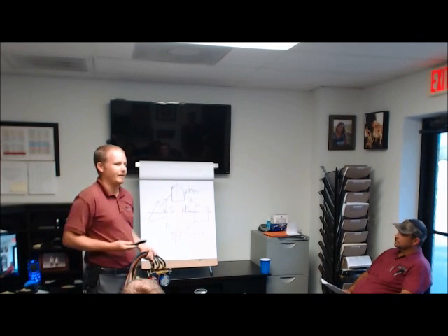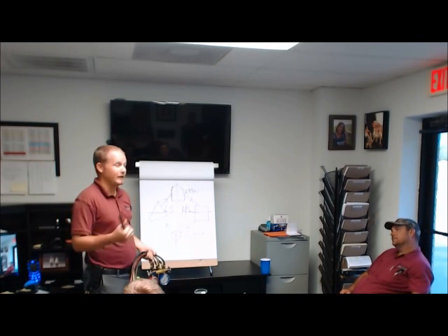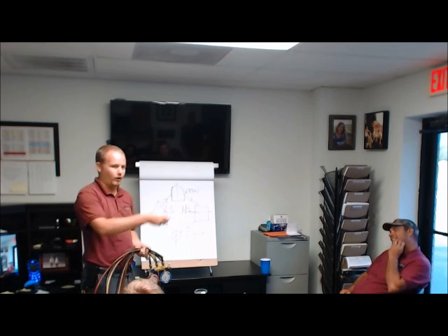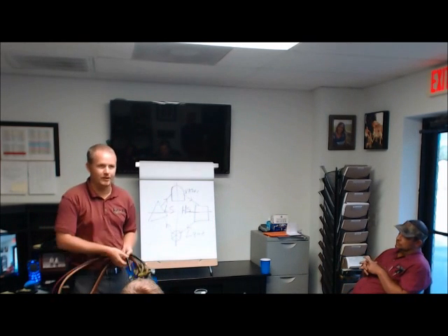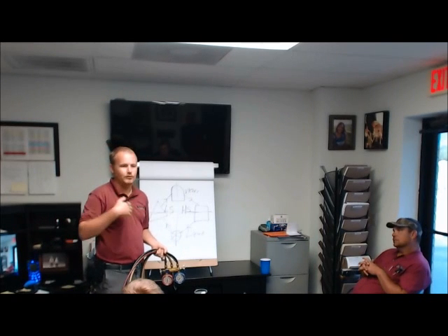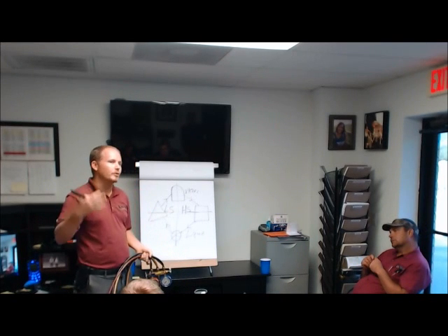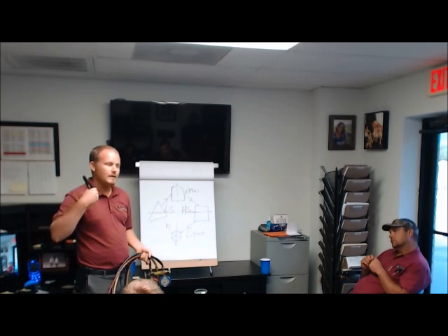You just start to kind of build on that, and then he taught us to feel through the system with our hands. All right, this is what a suction line should feel like. This is what a liquid line should feel like. Ouch, that's what a discharge line should feel like. No, seriously, because then it gives you an indication, especially when you're newer to the trade, to start to be able to tell.